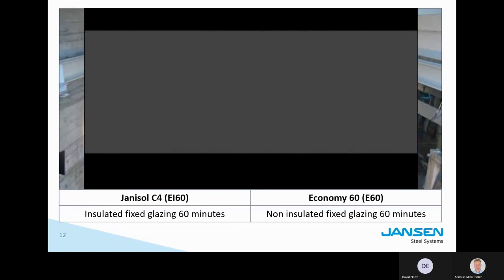Yeah. So if you're going to go with the E60, you need to make sure that you specify the correct kind of materials inside that space. Right. Because what you don't want is the self-ignition. This is, let's say, a dramatization of what happens. You probably would never put an E element in front of a chair or a living room or something, because you would have the self-ignition, which you don't want. You want to just keep the smoke and the fire out. The heat is in this case secondary. So in those sections of the building, you can use this type of class.